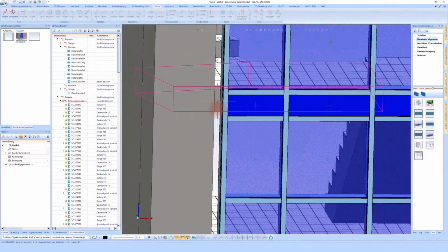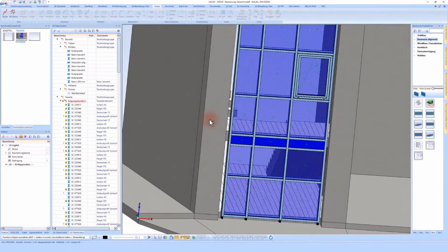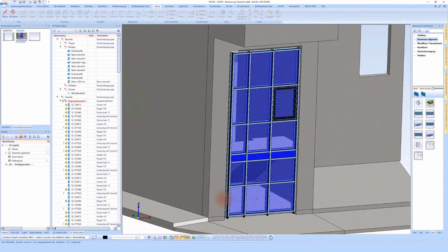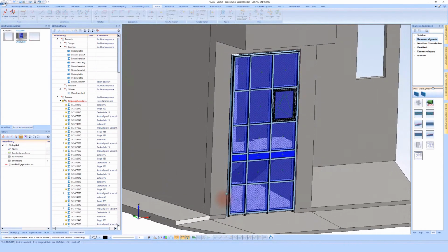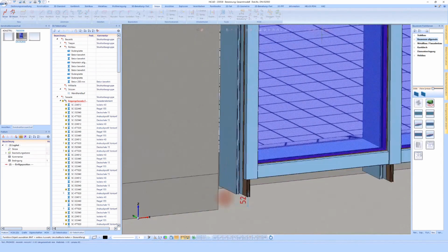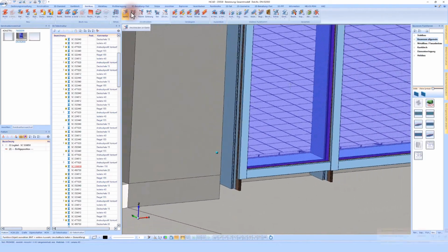Of course, you can also very easily change the edge distance of the posts from the wall and thus create things very easily. It is important that this always has to go through Logikal, and here it would obviously be a mistake if I were to use the standard HiCAD functions, because when I work in combination with Logikal, it is very important that Logikal also checks the maximum lengths to ensure that I do not create anything incorrect.